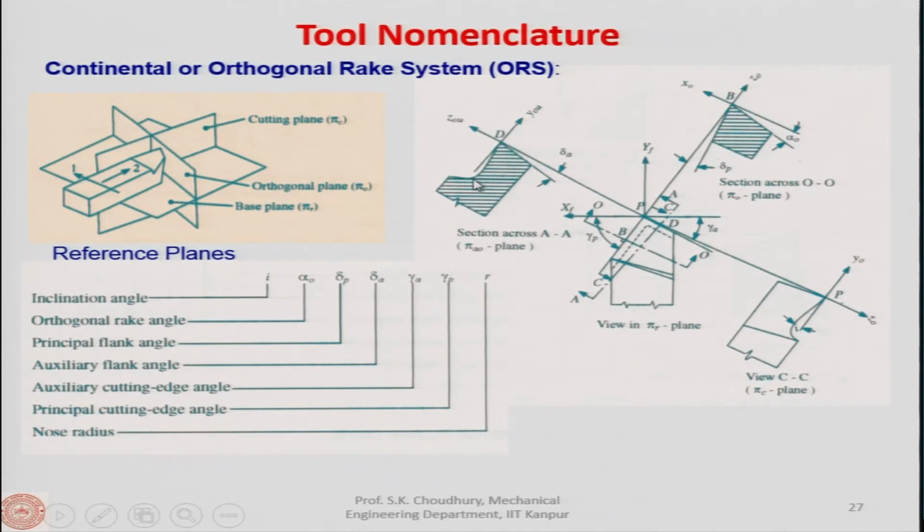face. Now I would like to point out one thing: the inclination of the rake face here and the inclination of the rake face here are different, because I said there will be more than one inclination on the rake face. Therefore, these rake angles, which define the inclination of the rake face, are called differently. I will tell you what those are.